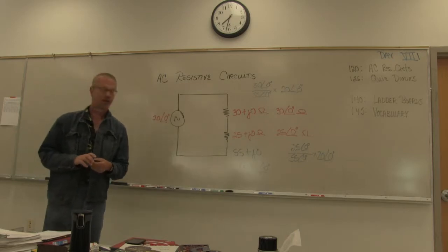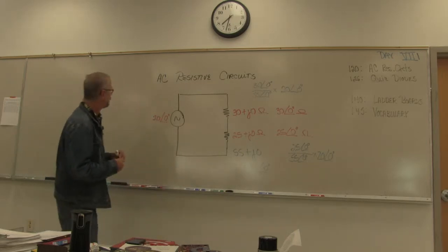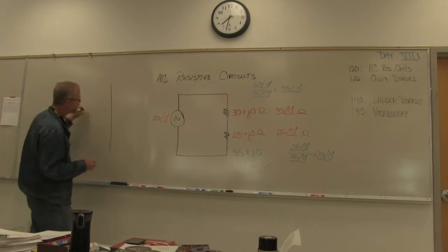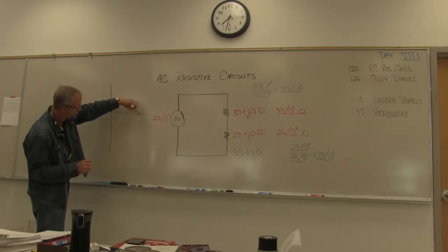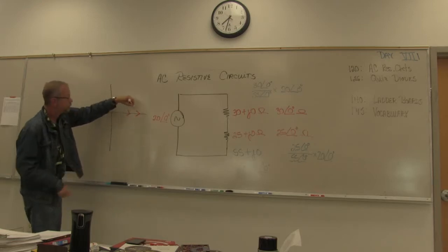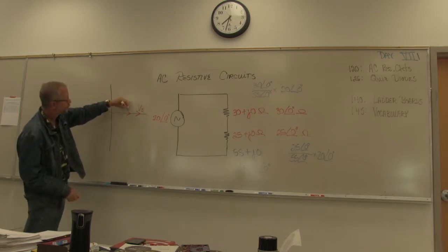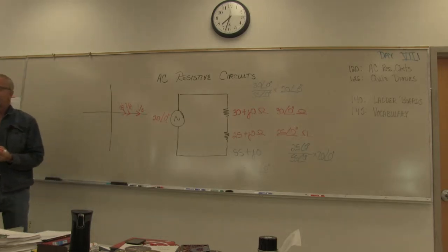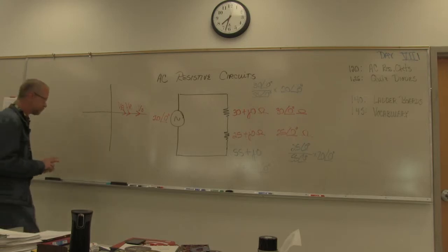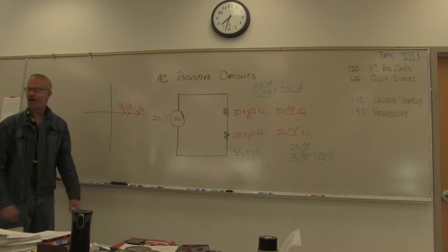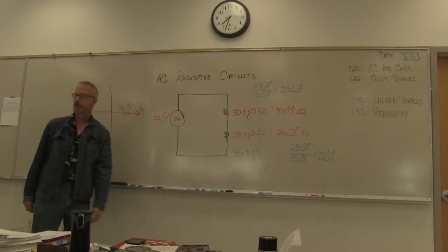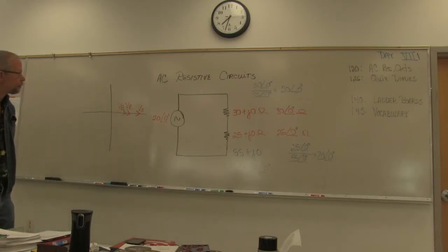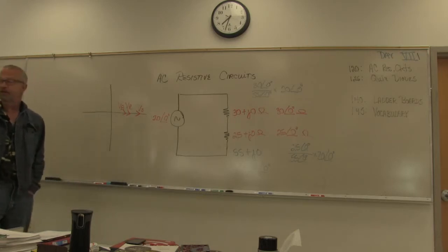Okay, the fact that it's at an angle of 0 means all of our vectors, everything that we have in this entire circuit, Vs, VR1, VR2, are all on the same axis. So there's no angles, there's no sines, there's no cosines to play with. We're dealing with the situation here where the sine is equal to 0 and the cosine is equal to 1. Angle of 0 degrees.